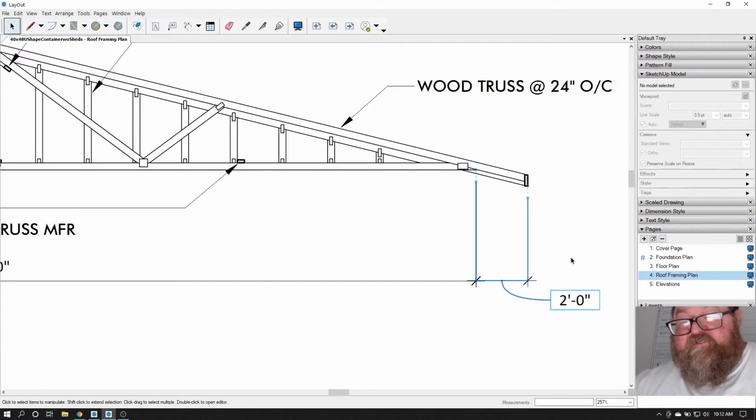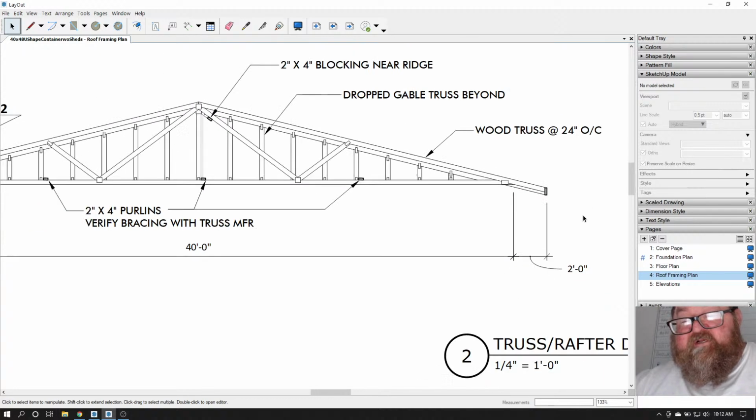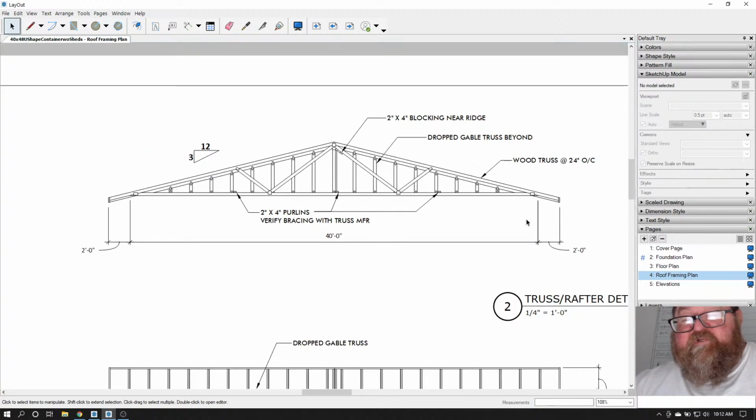Let's say you're using like 4x8 sheets of Hardie soffit, and normally you could just rip it down the middle and you'd have 2 sheets 2 feet wide. Well, if you make the soffit 2 feet 1.5 wide, now you're wasting a whole sheet of soffit material for just 8 feet. You could have got 16 feet out of it before.